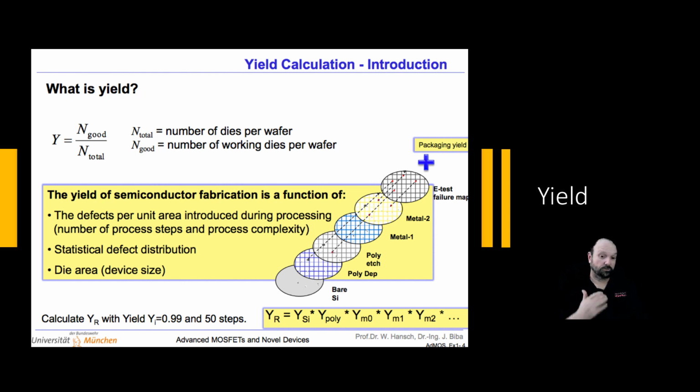Even if you're at 100% and you can only make 50 because they're bigger, you're still going to end up with fewer chips per wafer. So you're always balancing this equation. If I make it smaller, I'm going to have a harder time making it and lose more die, but then I get more die per wafer. So where's the sweet spot?